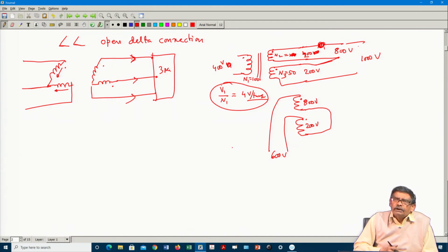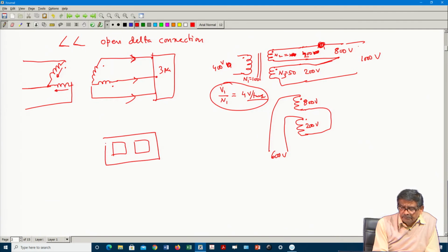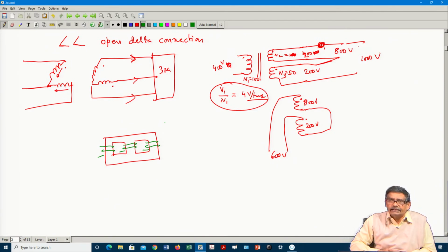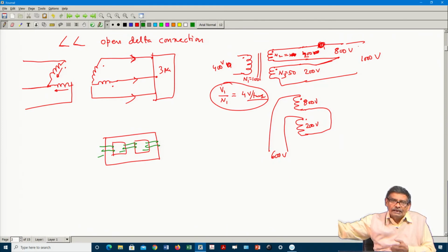But in case of a transformer, the coils are concentrated. If you recall, in a transformer, if it is a core type, 3 limb type, the coils are here, on this, only primary I am drawing, say. These windings are not distributed in space over 360 mechanical degrees. They are concentrated, just like coils, not like a winding with its return coil side present 180 degrees apart.